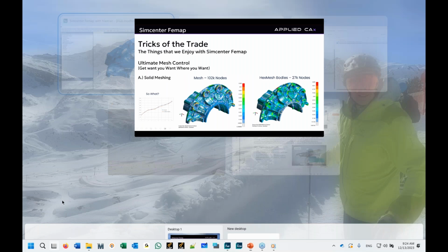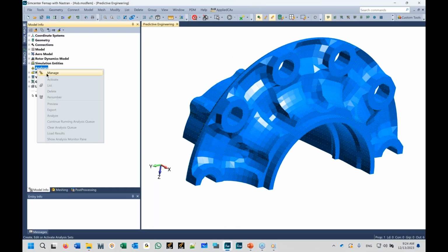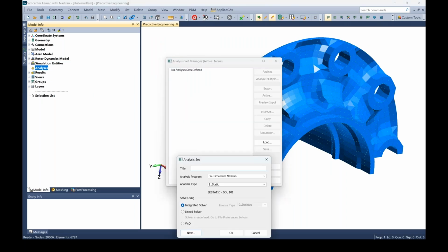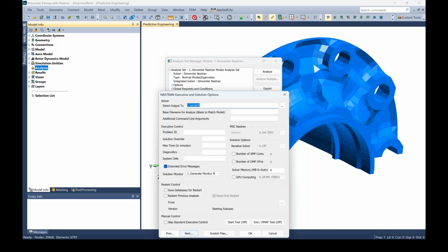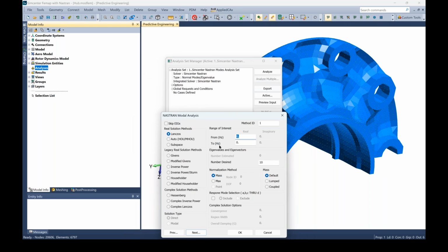If you're not familiar with that, when I'm talking about the free, I'm talking about no constraints. So you go here, normal modes, and I'll go into here because I'm not interested in mechanisms. First, I'll block this out. It says, don't give me anything under 1, which are the mechanisms. And then run it.